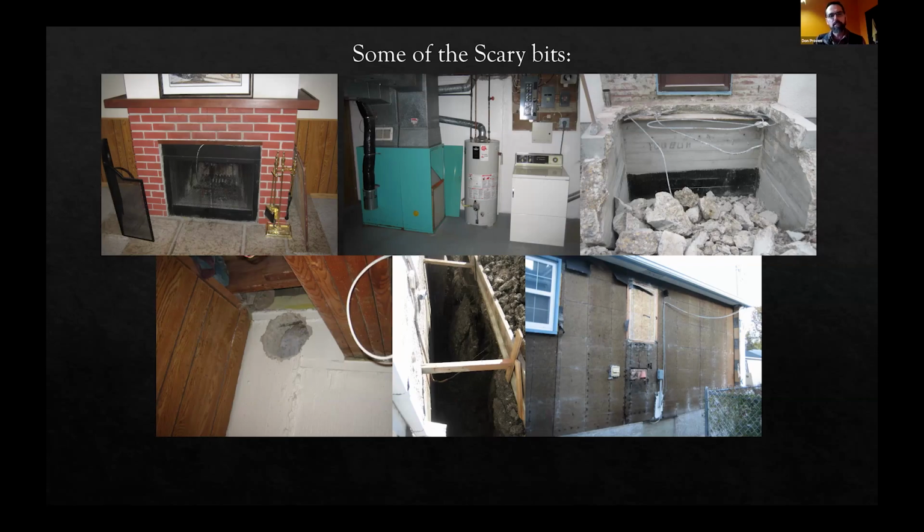There's a middle picture of the trench that we excavated. It's kind of hard to see, but because I was doing this by hand, the backfill is being kept out of the hole by some boards you can see. You can also see a flake of material that came off the side of the trench and fell into the bottom. That happened overnight, but that would have squished me like a bug. So trench work is dangerous, so plan accordingly. Make sure you have room for all that material. Plan ahead.